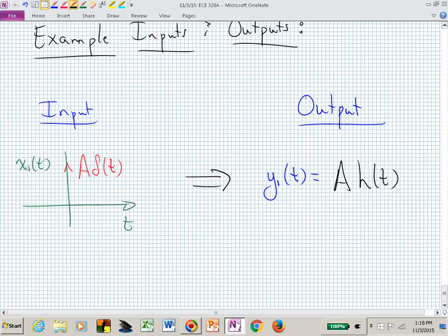And let's say that we had some first order behavior, a first order filter. This might look like that. That might be our y sub 1 of t. That's a legitimate decaying exponential for a first order impulse response. So we hit this system with an impulse and we get this exponential decay.